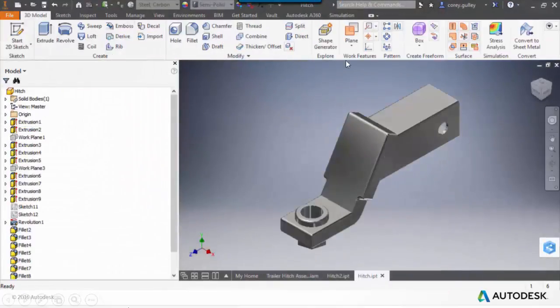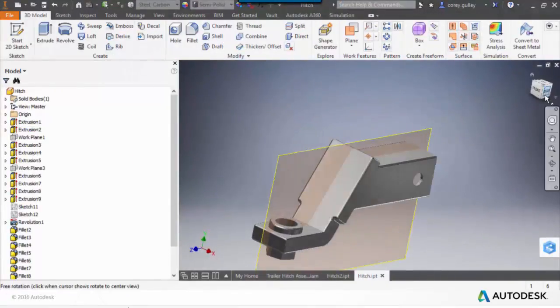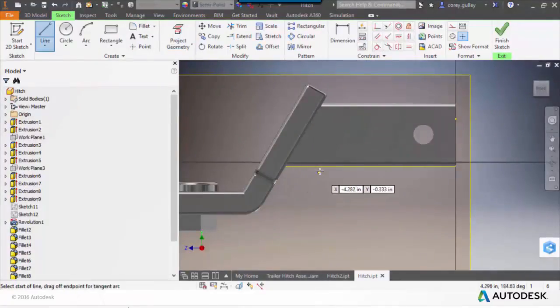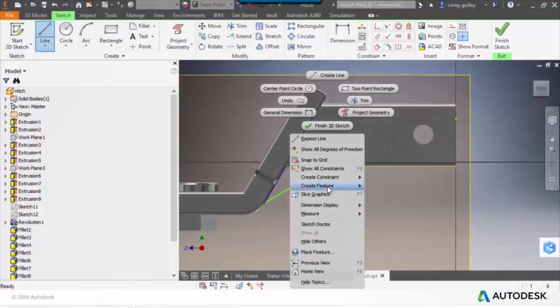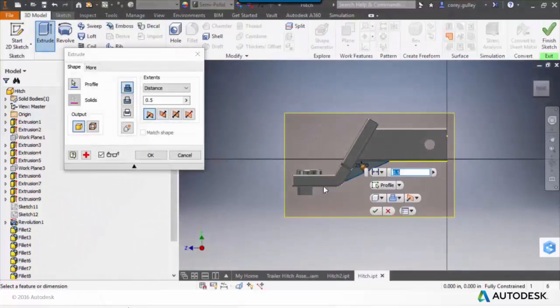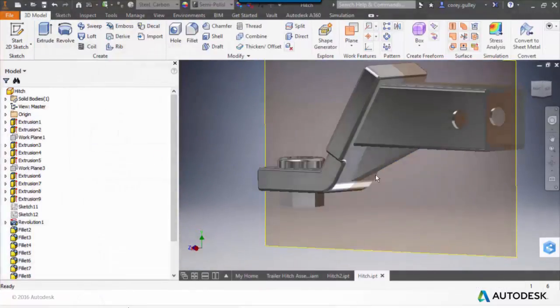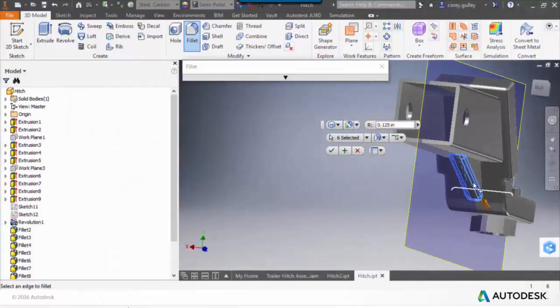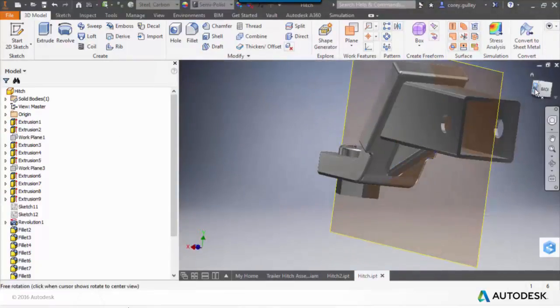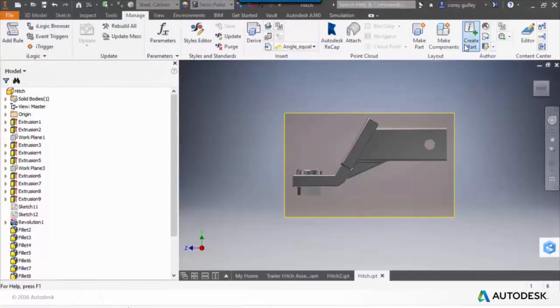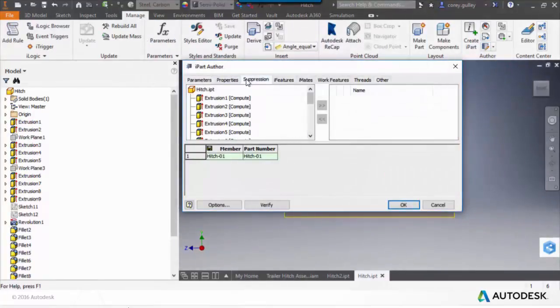Now, whether you're working inside of Inventor or inside of SolidWorks, we work with both. But the first thing I noticed whenever I looked at my results is the maximum displacement was really due to a lack of stiffness that I had in this vertical direction. So what I may do here is go into the CAD environment and add some sort of stiffening rib so that I can stiffen up that particular direction and reduce that overall deflection so that I can come up with a more optimal type of design.